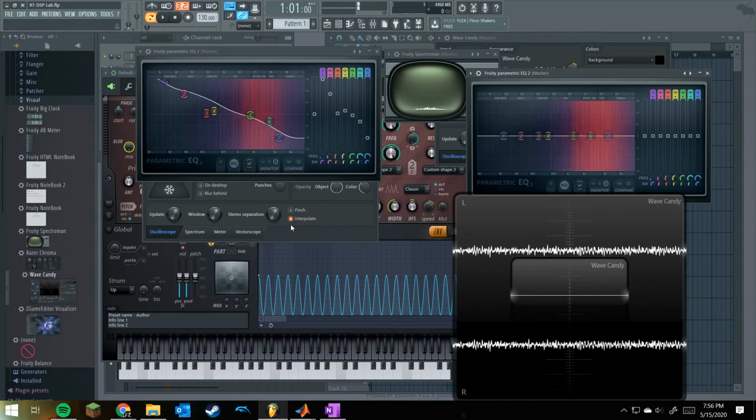Perfect. That's what I like to see. So, as you can see, in the pass band, we expect it to be between 1,500, which is about right there, and 5,000, which is right there. So between here and here, yeah, obviously. So that was just the impulse invariance form of the filter.